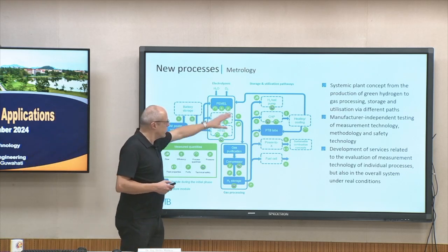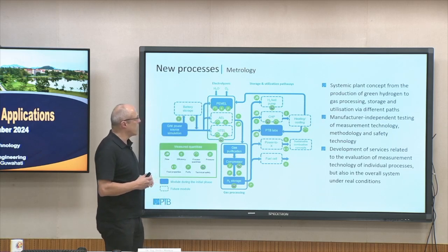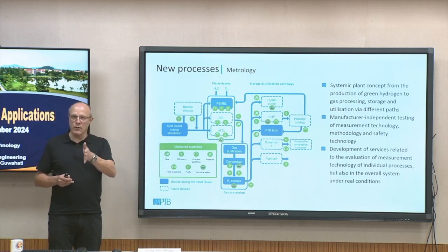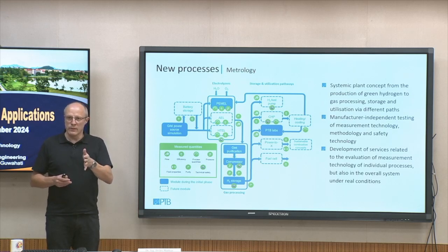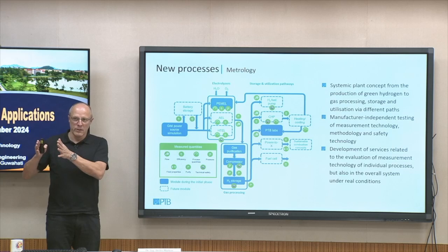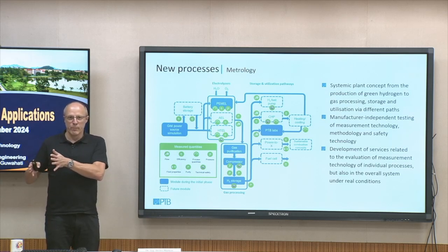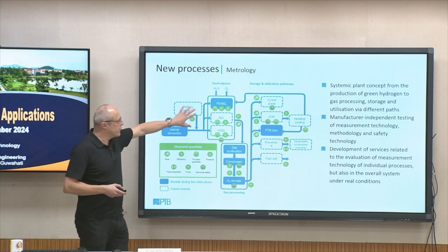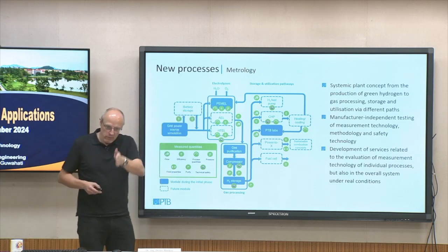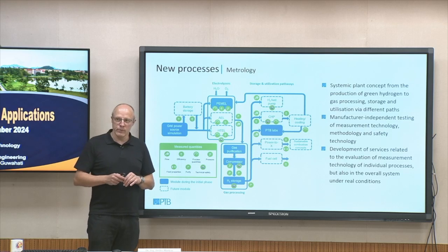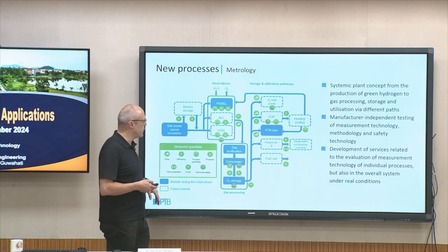Or here, if we consider such an electrolyzer, what about safety if there is a rupture of your diaphragm in the electrolyzer? We have a pure hydrogen atmosphere, we have a pure oxygen atmosphere. So the worst case is directly existing here, and only some millimeters are responsible for the safety.